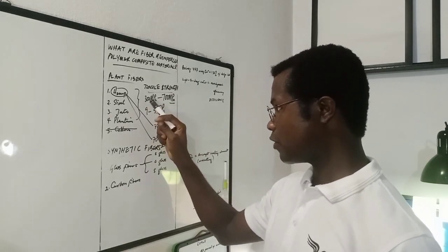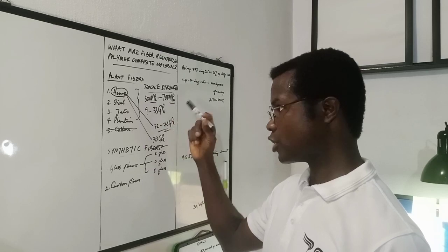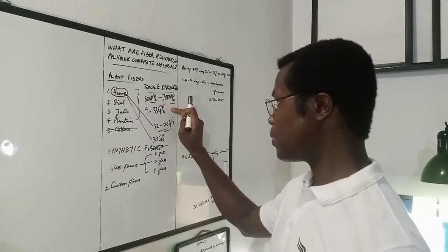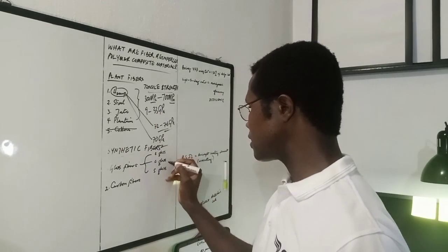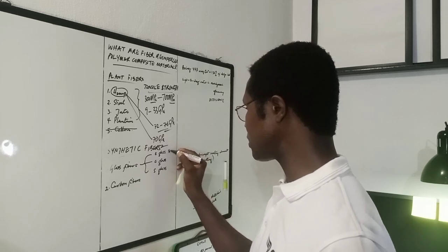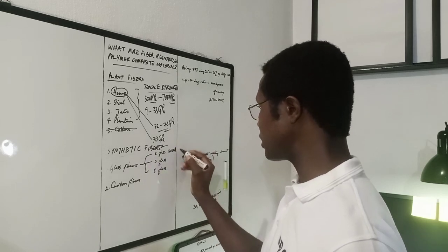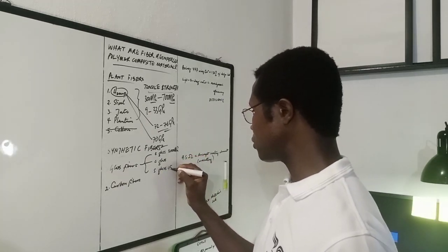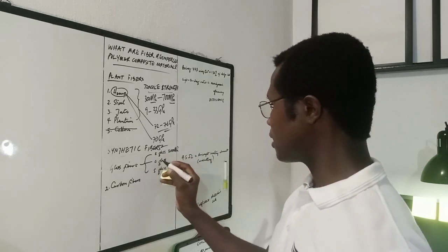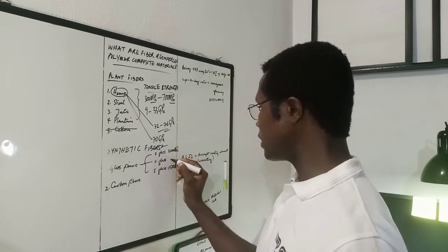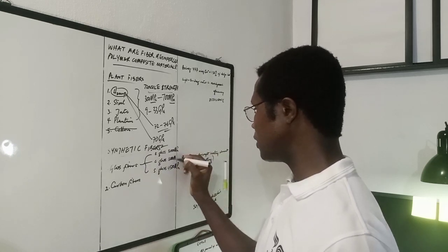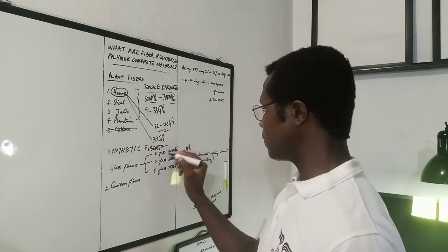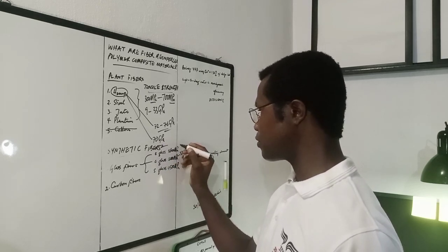So as I was talking about the range for natural fibers, 300 megapascals to 700 megapascals in general, you're going to have small exceptions to this rule, but they usually don't go very far from these numbers. 300 megapascals to 700 megapascals for tensile strength. With E-glass, C-glass, and S-glass, they fall somewhere between 3,000 megapascals. So you can see the difference, 300 to 700. But here you have 3,000 MPa, megapascals. Structural glass can be up to 4,500 megapascals. The C-glass in general is somewhere closer to 3,000 MPa to 3,300 MPa. E-glass is closer to 3,400 to 3,500 MPa. Okay.